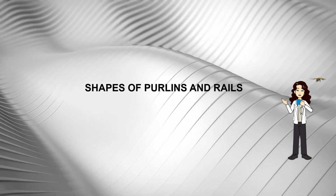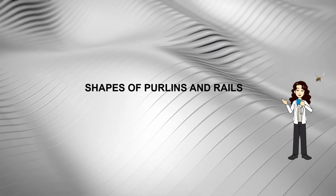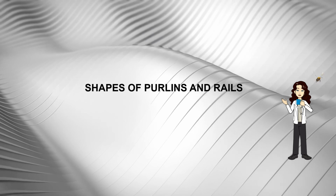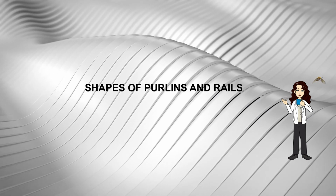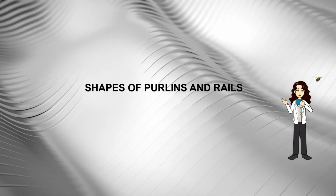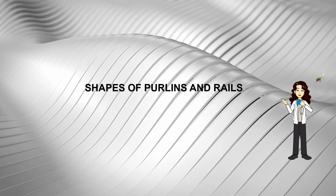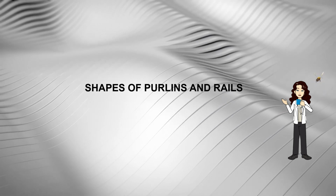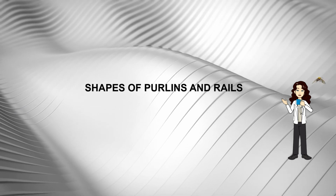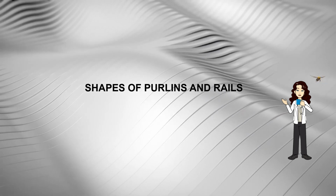Shapes of purlins and rails. Although some long-span cladding systems are available which will span up to 6 meters, most portal frame structures are designed with purlins and rails supporting the cladding and spanning between the main frames. The spans between frames are between 4.5 and 10 meters, with 6 to 7.5 meters being most popular. Roof decks of larger span are used primarily in flat roof systems and are supported directly on the trusses.